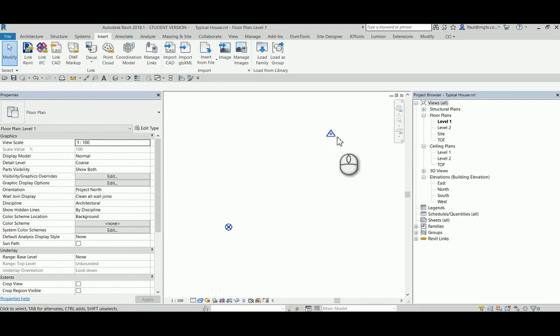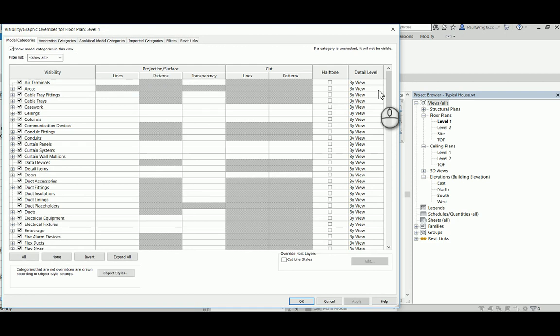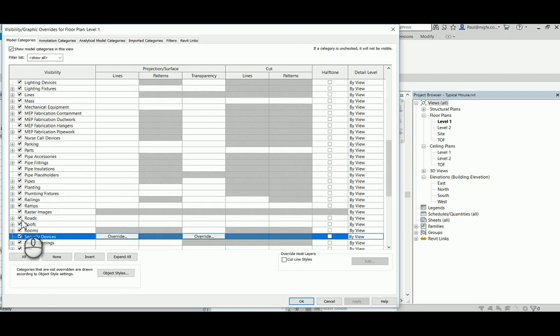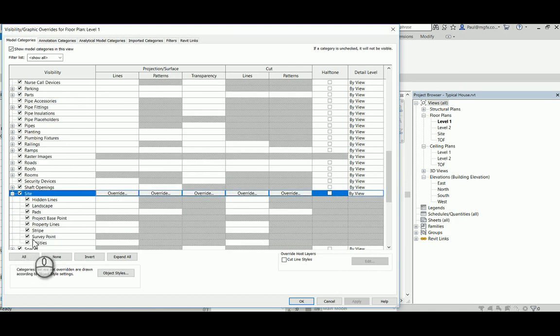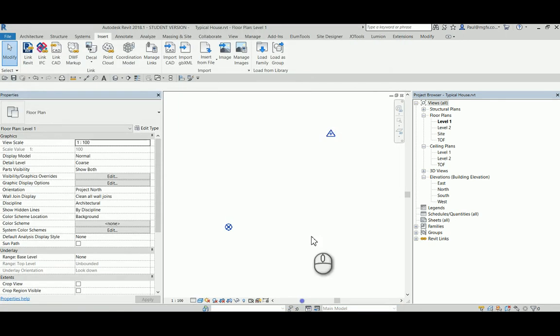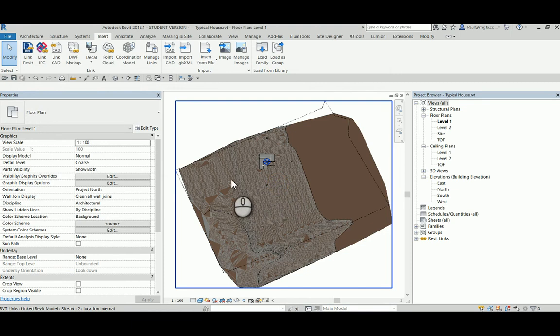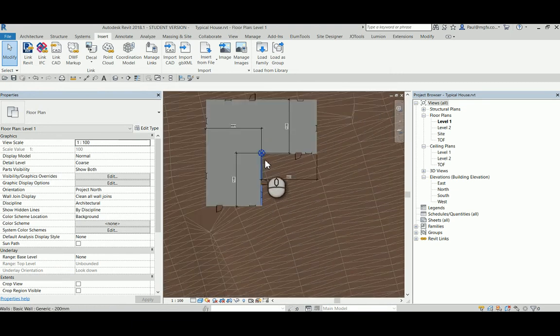It's just that the shared coordinate system has now been published, so the site marker is way off over there. Easy way to handle that. Either switch off the survey point if you need to keep it exactly where it is and zoom in to extents, or otherwise unclip the survey point and move it to the project origin or something like that.